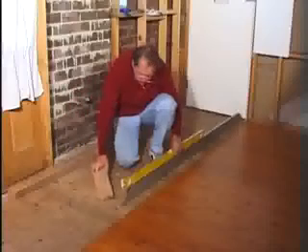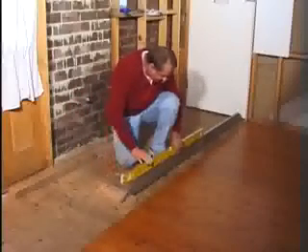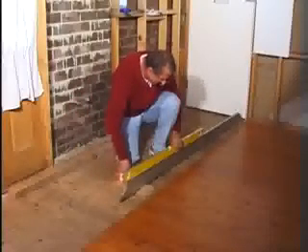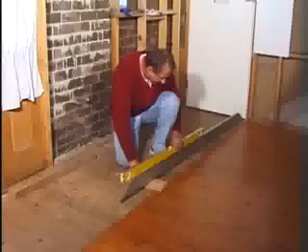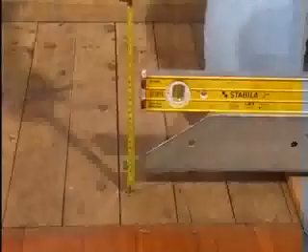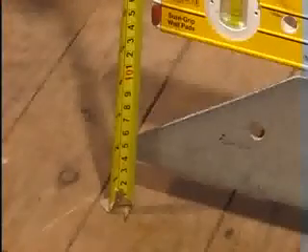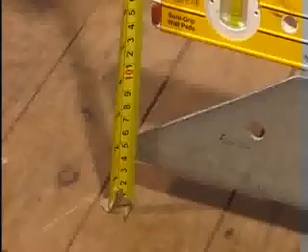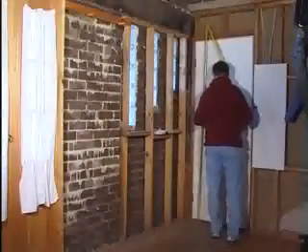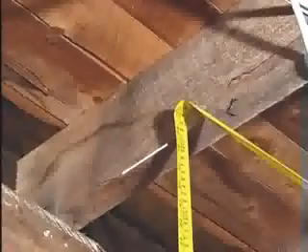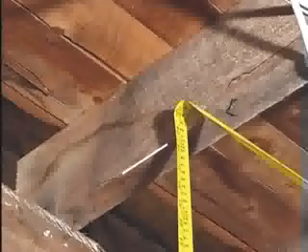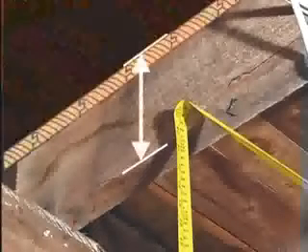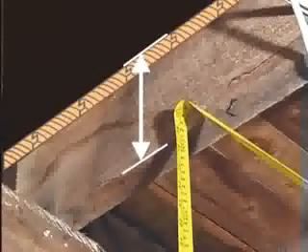On a renovation job, accurately measuring for a staircase requires several procedures to be followed. Over the years, settling may have caused floors to become out of level. The amount of error, if any, needs to be known for later calculations. With no opening prepared for the stairs at this stage, the height measurement is taken to the underside of the upstairs floor joist, and the depth of the flooring and joist is added.